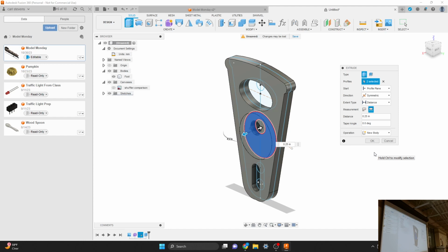So you measure the width of the belt and the thickness of the belt, then it has a thickness, and it has radii proportional to the thickness of everything else. It has a line width, internal length, and relative thickness. There's a constraint called belt coincidence. Now it's all done parametrically, connected with user-defined parameters.